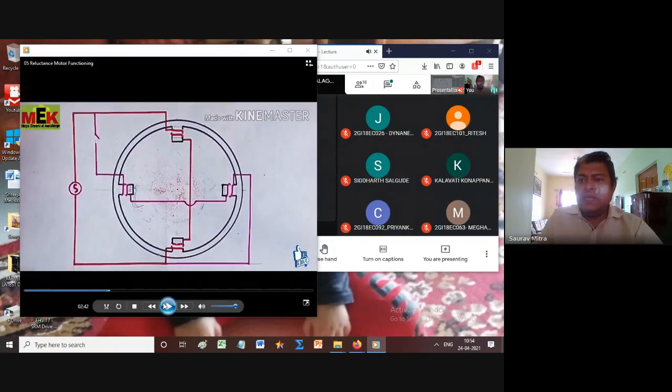So he is using a single phase SRM, but we have used a 3-phase SRM, because a 3-phase SRM has higher power capacity, so the number of phases does not matter. In the single phase SRM they are using, the single phase has been split into 2 phases. We can find it here, and those 2 phases create the rotating magnetic field.